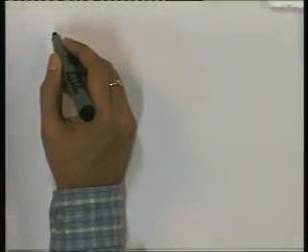So, to draw the constellation, what should we do? We should find an orthonormal basis for the signal set generated, the subspace generated by the signal set. Here we have all these orthogonal signals, so the only thing we need to do is scale them so that the length of each signal is 1. Then that will give us an orthonormal set of vectors, because they are already orthogonal. So we need to only scale them appropriately to have length equal to 1 for each of the vectors.